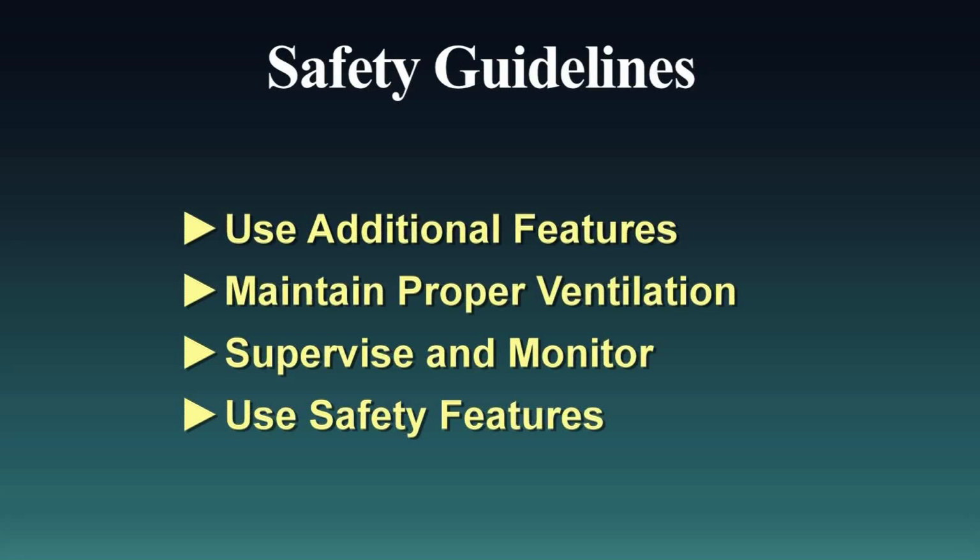Maintain proper ventilation. Ensure that the room where the heater is placed has adequate ventilation. If the room is poorly ventilated, it may lead to a buildup of carbon monoxide or cause the air to become dry. Open a window slightly to allow fresh air circulation.